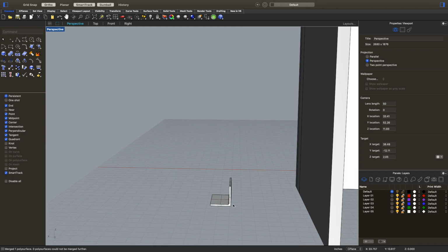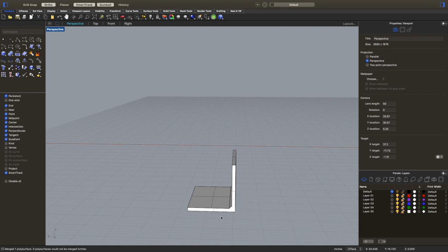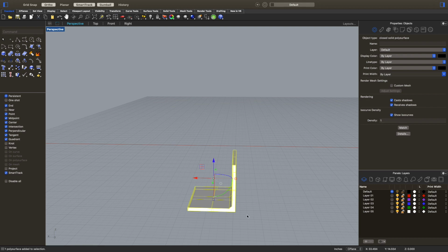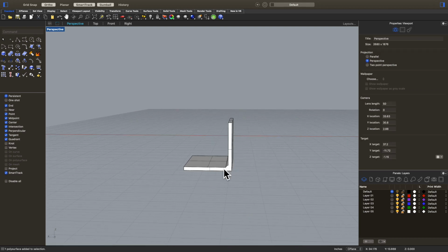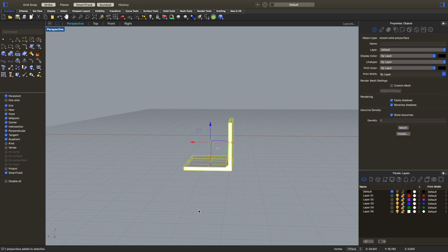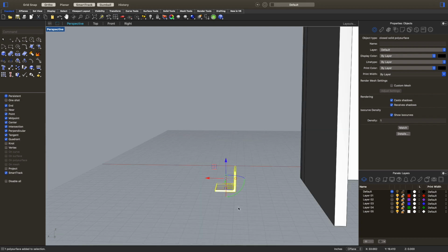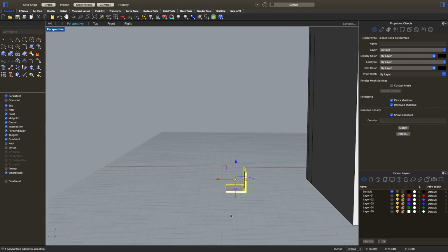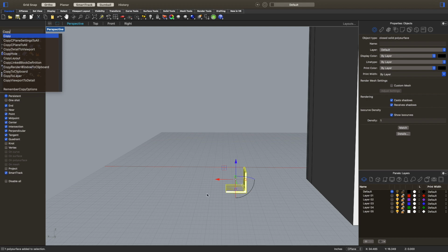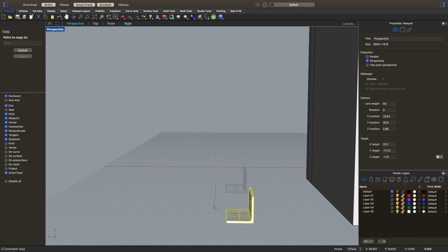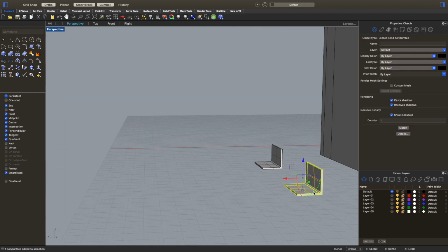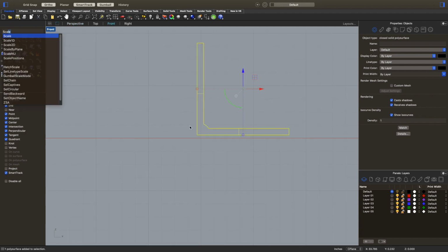It's a smaller hinge. It's 3/4 of an inch by 1.5 inch hinge. And we can either make this smaller or we can start with a new one. But I think I'm just going to scale this down. So I can do that by typing copy, enter, selecting the object, clicking and dragging to make a new piece, hitting enter to get out, and then I can use the scale tool. So I'm going to go to the front view and type scale, enter.